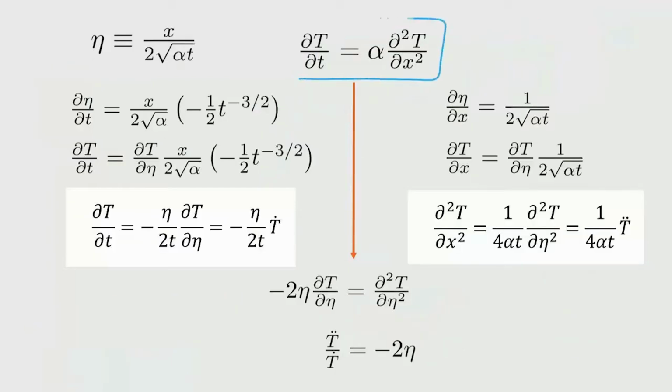So, this is the governing equation, and we have got this substitution that is being used. So, dou eta by dou t can then be straight away seen that it will have this coming here, and then 1 by root t, t raised to the power of minus half would differentiate to give minus half t raised to the power of minus 3 by 2. And then when you look at the first term on the left hand side, dou T by dou time, that will be given as a differentiation by parts.